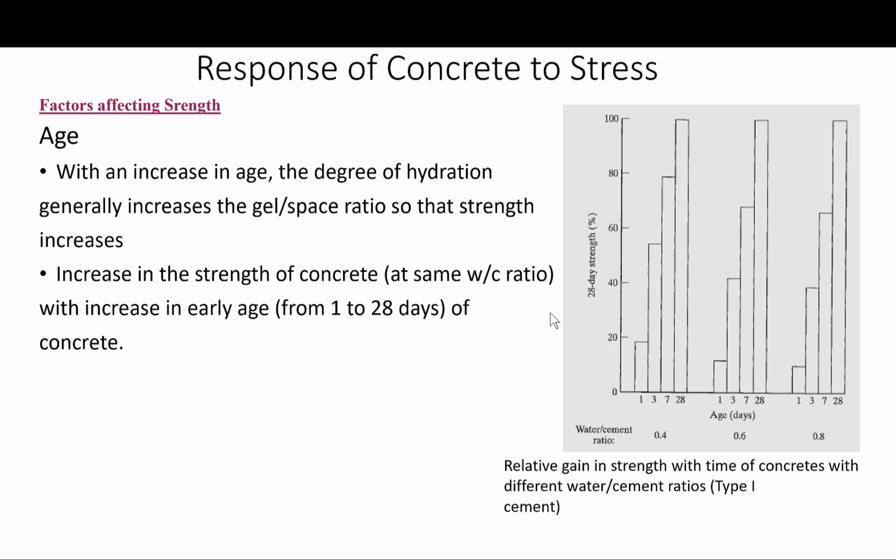So the unhydrated cement particles contribute to the initial strength gain as hydration begins, but do not really provide additional strength over time, since they represent portions of cement paste that do not really form hydration products. Okay, so there are two other practical questions that should be asked here.